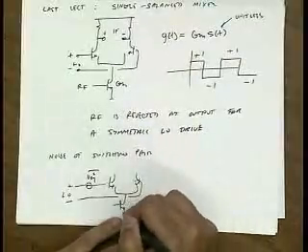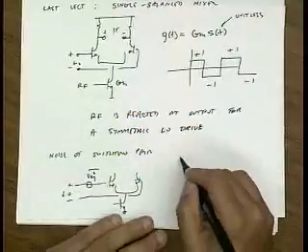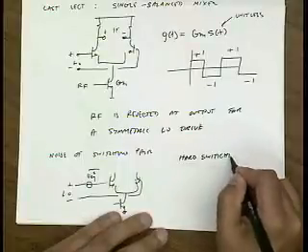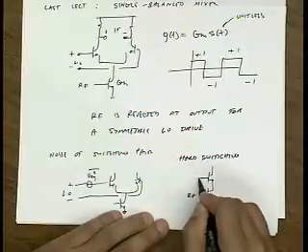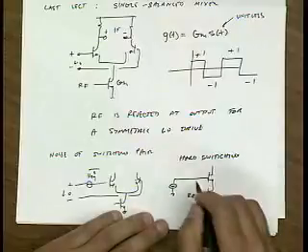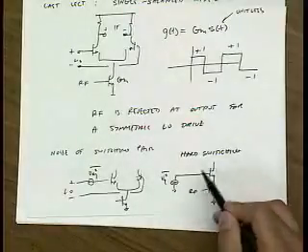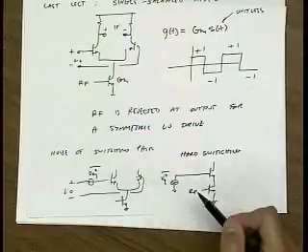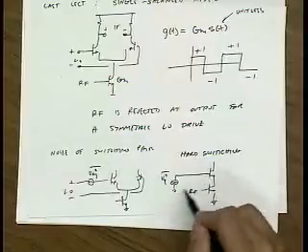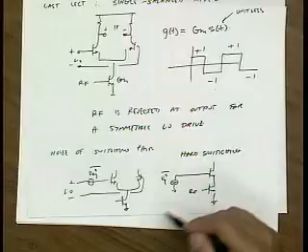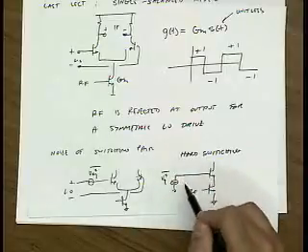Now, the important observation to make is that if I swing this differential pair very hard, so for hard switching, the equivalent circuit is always something like this. The AC equivalent circuit from the RF port. This V equivalent essentially looks like a cascode circuit because this device is turned off by the hard switching action, or vice versa. And as we studied in LNAs, a cascode configuration will reject the noise of this device, right? So the noise is rejected by 1 plus GM RO of the device. So the noise to the output is actually very low due to this device.